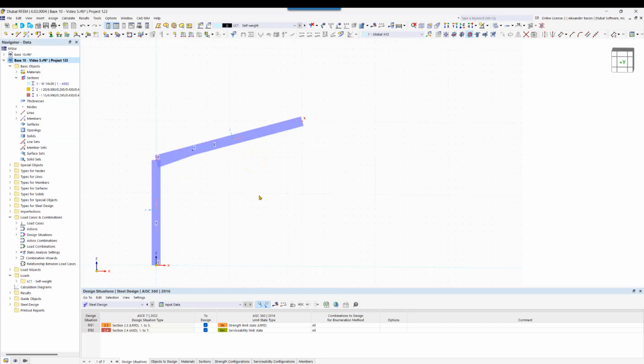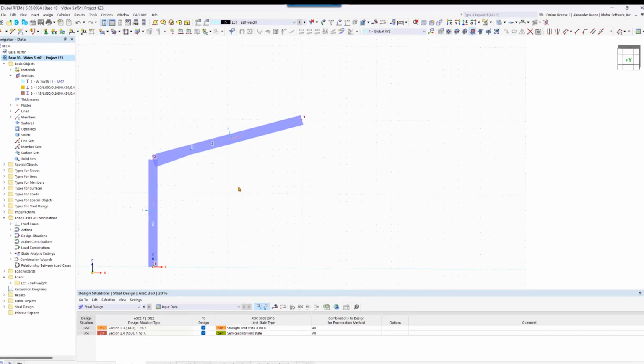We exit the input by right-clicking, and since we are modeling a 3D hull, it must be sufficiently stiffened to be able to insert bracings and purlins more efficiently. So during this tutorial series, we will add internal nodes to the two members. We have several options for this. We can decide to simply divide the members into intermediate nodes by right-clicking. We activate the Node on Member option so that nodes are created on the members without dividing them.